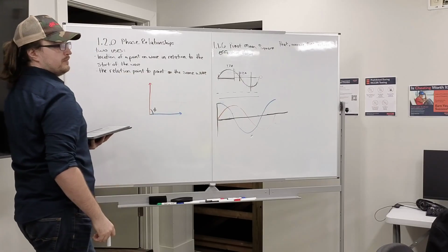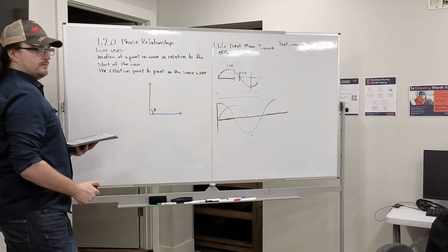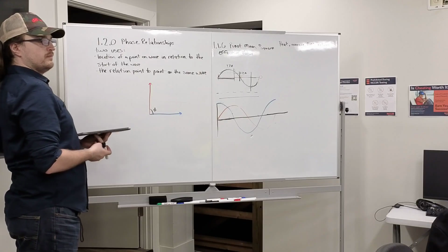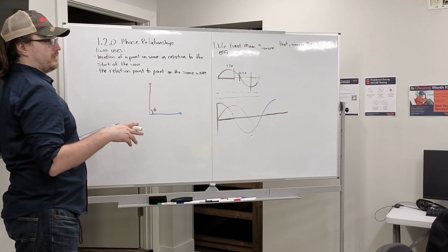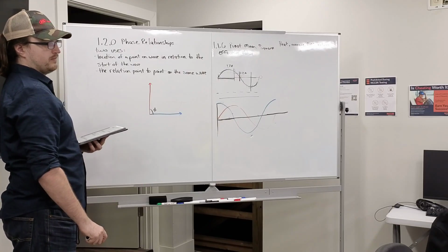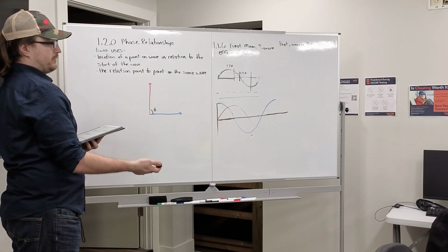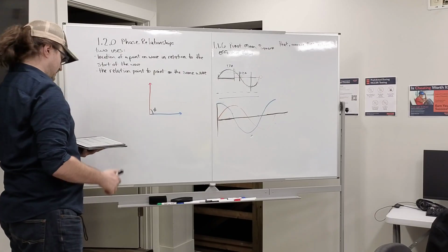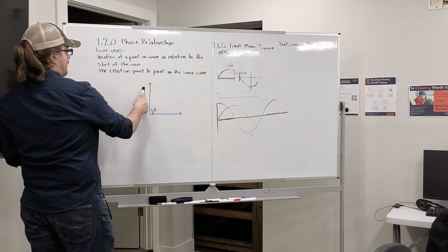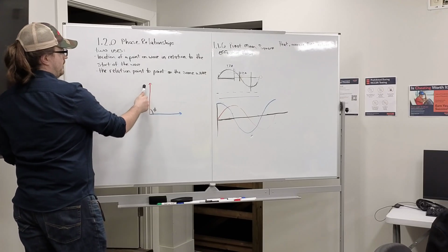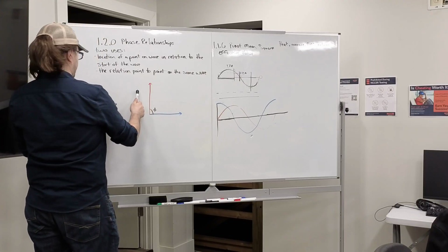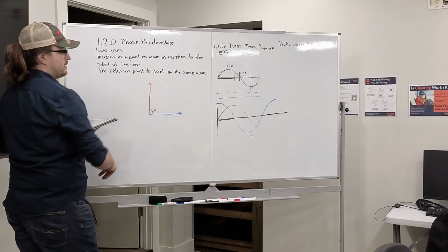Could that technically be like two different phases of wire when you're pulling 3 phase? Yeah. When they say phases are out of sync, those are not 90 degrees. In 3 phase, they're 120 degrees out. There are 360 total degrees, each one 120 off. So the equivalent of this is one generator starting its cycle at 90 degrees and the other's angle starting at 0. One started at max, one started at min.